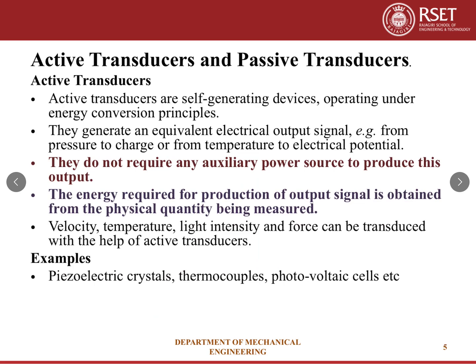First we will discuss active transducers and passive transducers. The first is active transducers. Active transducers are transducers which do not require any auxiliary power source to produce their output, or they can be considered as self-generating devices operating under the energy conversion principle. They do not require any external power source. They generate an equivalent electrical output signal based on the input.